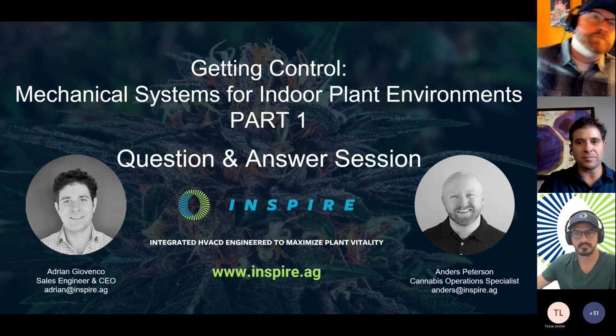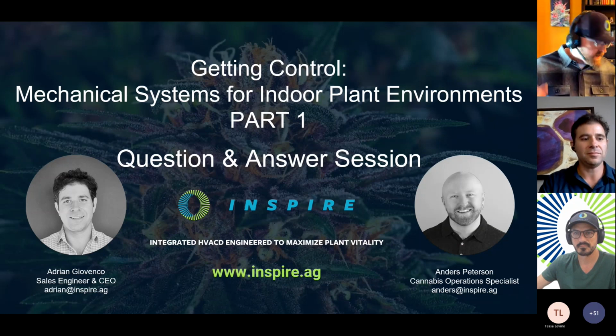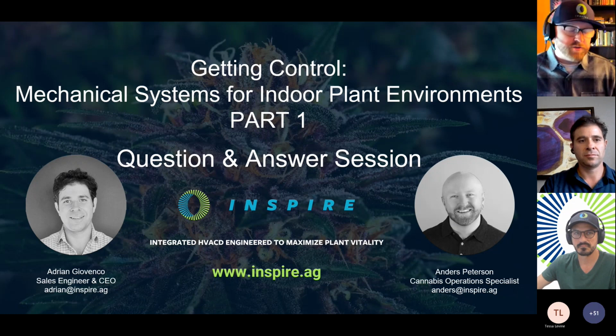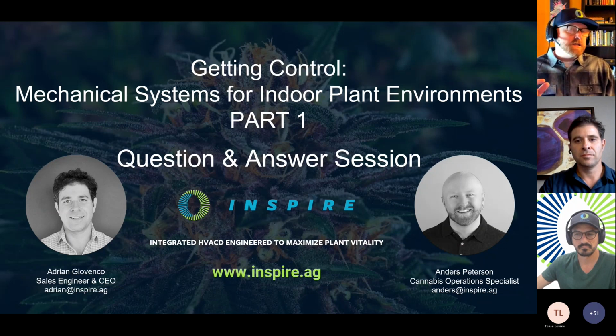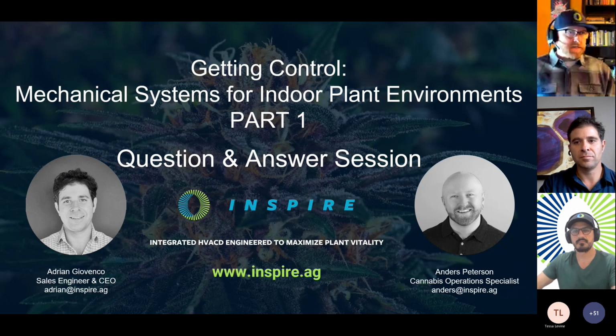Yeah, sure. Typically, because of the infrared radiation or the radiant heat that HPS fixtures give off, oftentimes the leaf temperature can be higher in HPS rooms or the offset can be less than in LED spaces. But that is not always consistent, depending on the lighting design and room design, such as the mounting height of the lights and how big the space is.